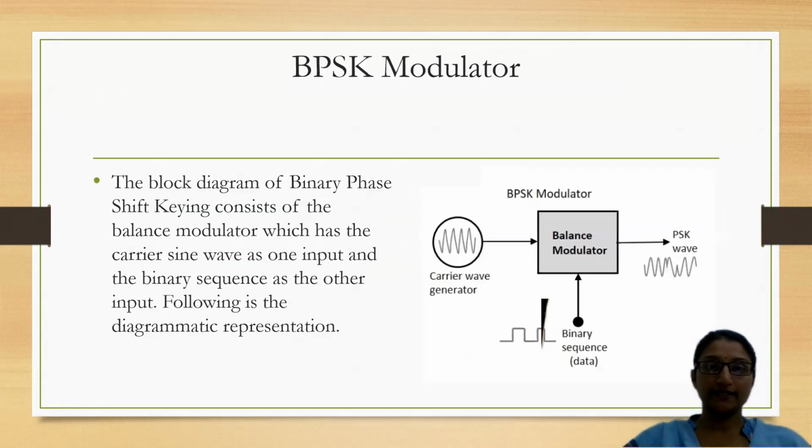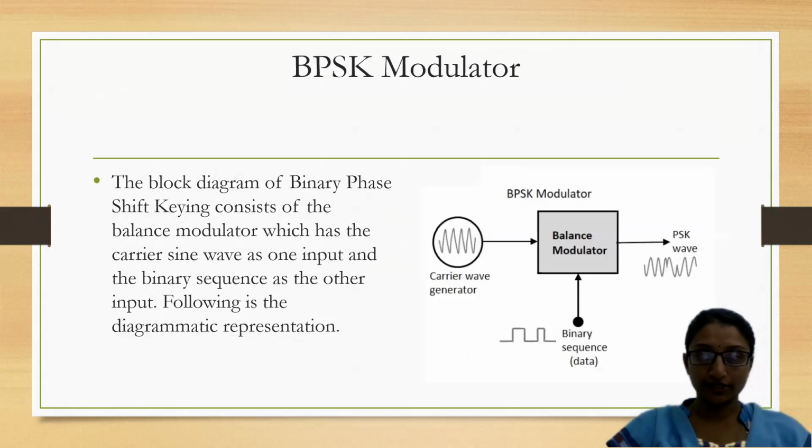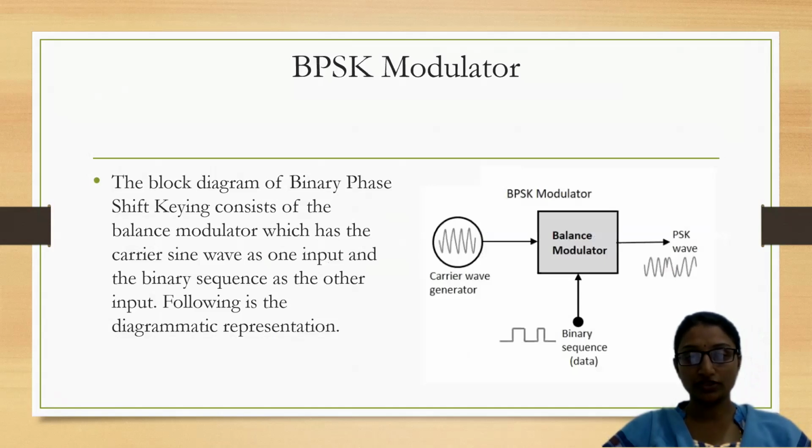Coming to the BPSK modulator, you can observe the block diagram. In the BPSK modulator, the balanced modulator is given one input from the carrier wave generator, the other input is the binary sequence data, and the output is our PSK wave. Right.